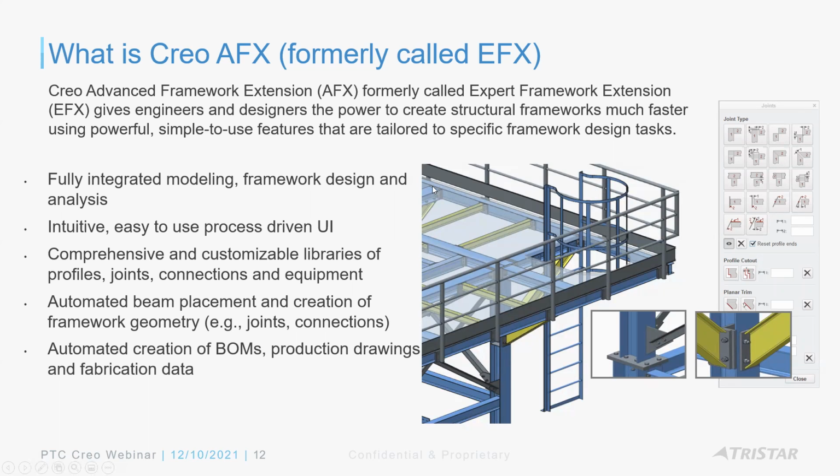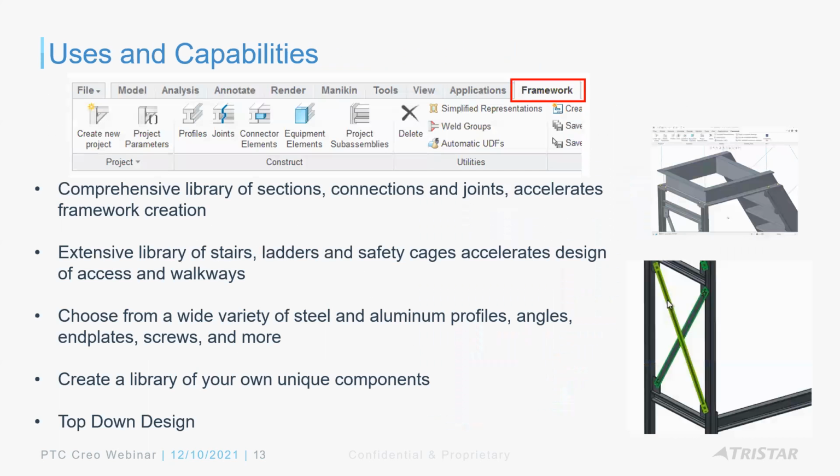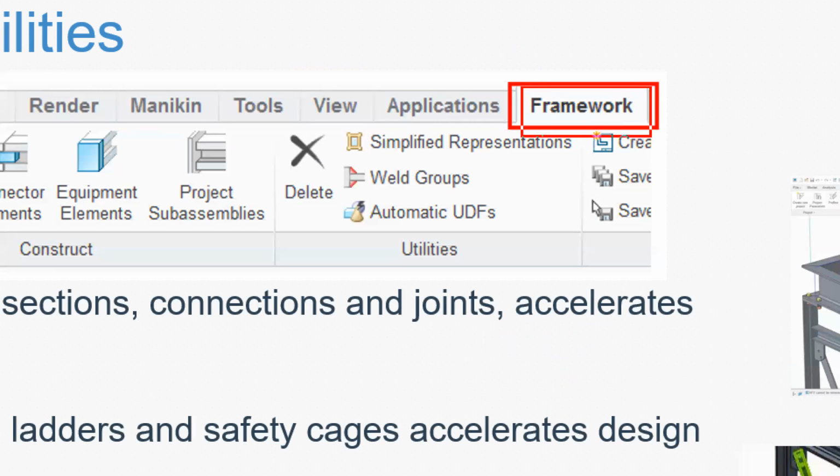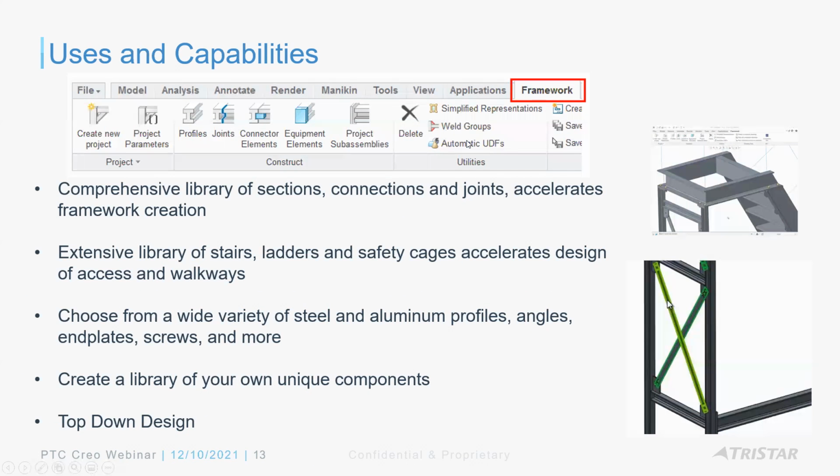in the traditional approach, you don't have to model the part and then create the assembly. You're essentially able to get into its own modeling environment that's specifically created to apply specific profiles that they have built in the software, which you can customize, right? You almost start with like a skeleton or a curve. If you see the steps for it, you just go into your assembly, and then you start with framework. There it is.